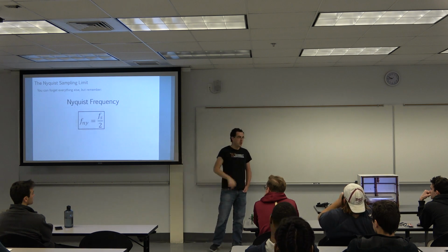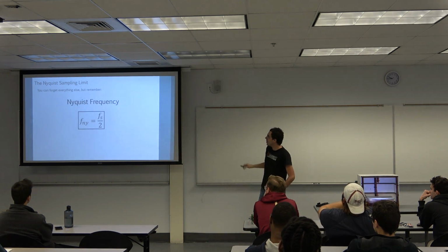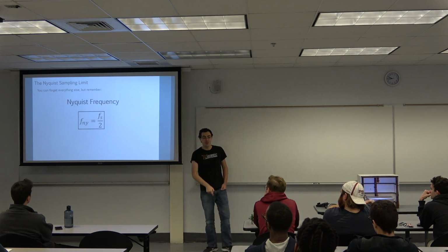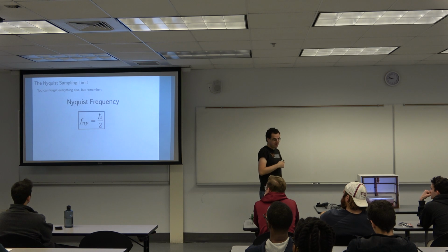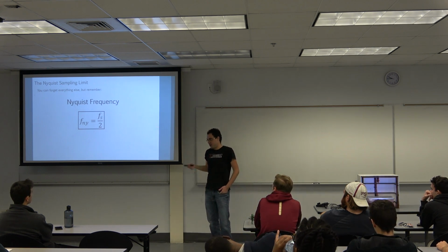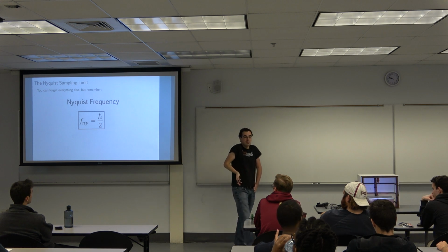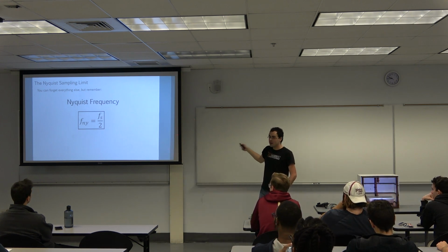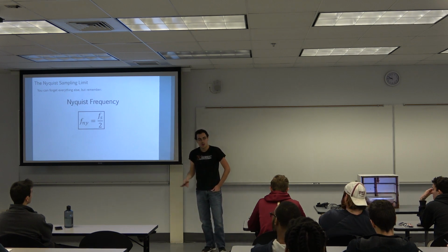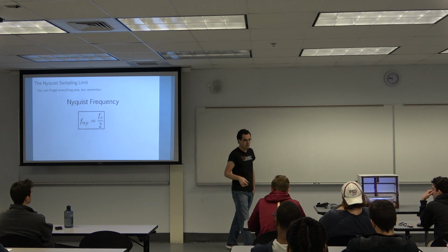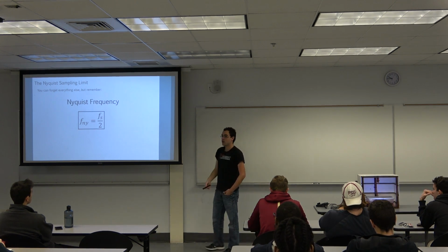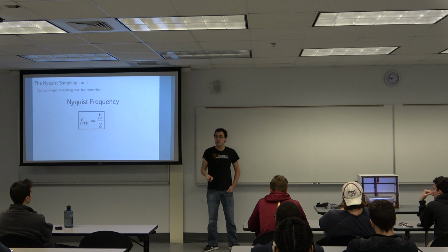So for this first part of the lecture, you can forget everything, but just remember that the Nyquist frequency is half of the sampling frequency, and that if you're sampling at a given sampling frequency, you have to remove the content at frequencies higher than the Nyquist, so you can be sure that you're not fooling yourself into believing a tone or frequency is present in your signal, which it isn't. And this can destabilize the control system, of course.